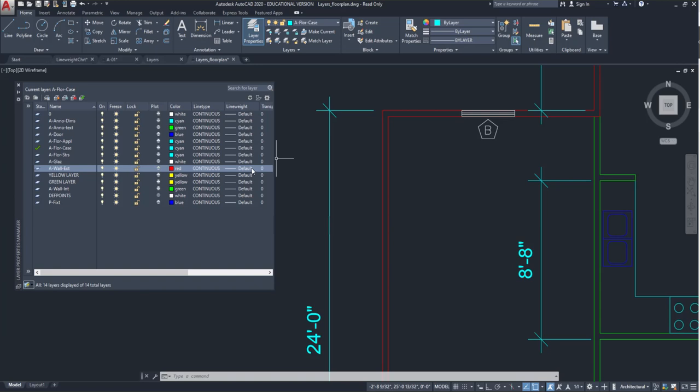But the overlying theme is that when we print them, we want them to have line weights, all right? So going back to the idea that AutoCAD is very generic, okay? There's two ways that we can print our line weights to have a thickness. We can use a pen file, which is the way I'm going to show you how to do it, okay? I'm going to give you a pen file, not today, and I'm going to show you how to use that pen file to make AutoCAD print your lines the thickness they should be, all right?